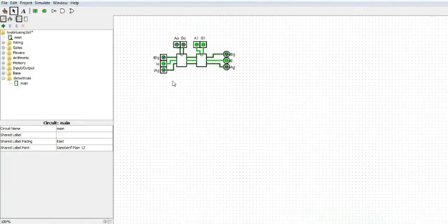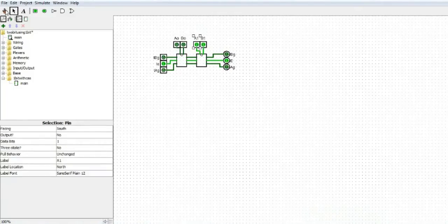So as I said earlier, initial setup: select the poke tool. See, everything is equal, right? We are not getting the equivalent pin output on the final stage raised to 1. It was still 0. So this is the initial setup. Cascade pin A equal to B should be connected to the VCC, and cascade pins A greater than B and A less than B should be connected to ground.